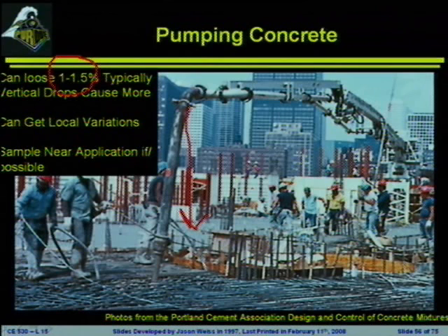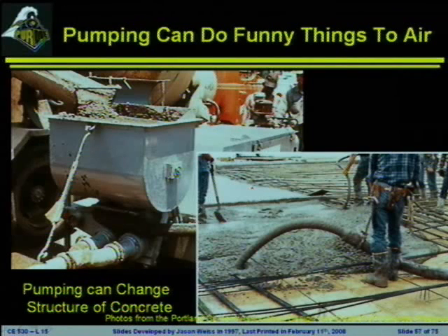One of the things I will point out, and we'll talk about this a little bit more in placement, is that it may not seem like the pumping process could affect the concrete dramatically, but it can. This is especially problematic when we start to talk about air contents in the mixtures. As mentioned, pumping can do very funny things. We will talk about the pump in greater detail, but the basic idea is it's going to go through a hopper here, it's going to go through a system, and then it's going to come out the other side and it's going to be placed.